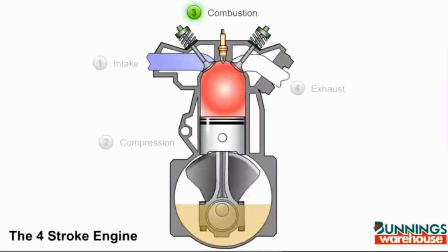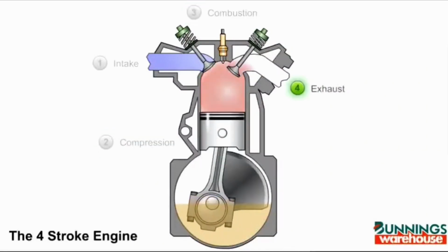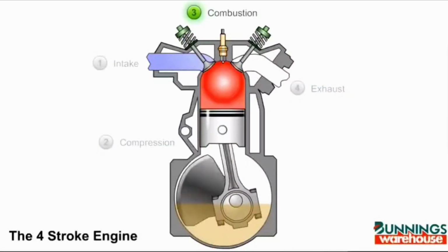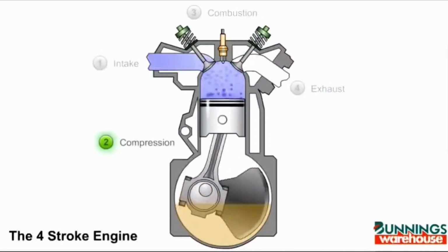On the last beat, the exhaust valve opens and the piston moves up again. This pushes the burnt gases out of the cylinder through the exhaust system. Then the whole cycle repeats again from the intake.